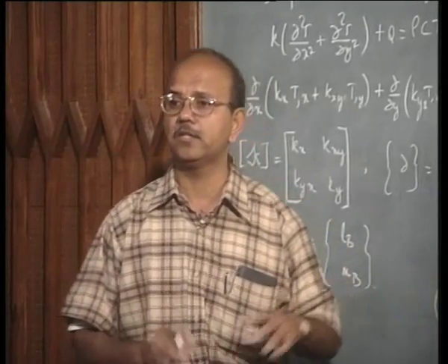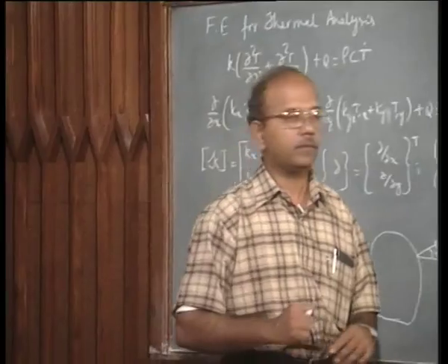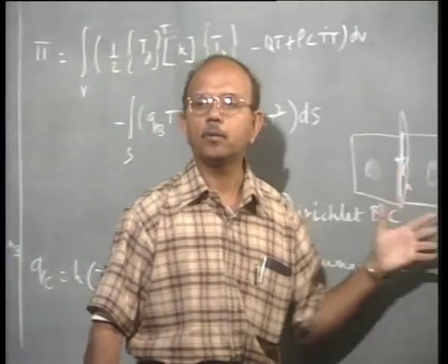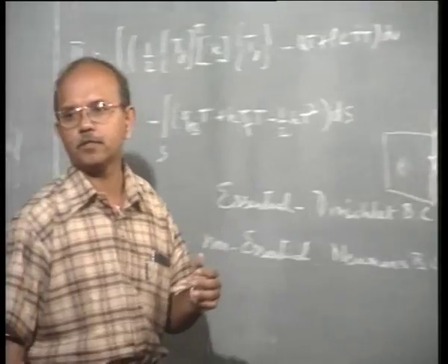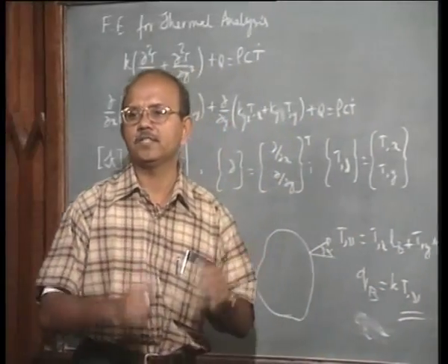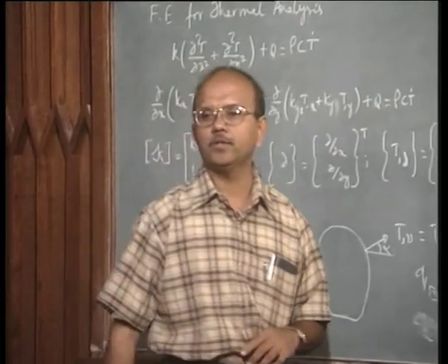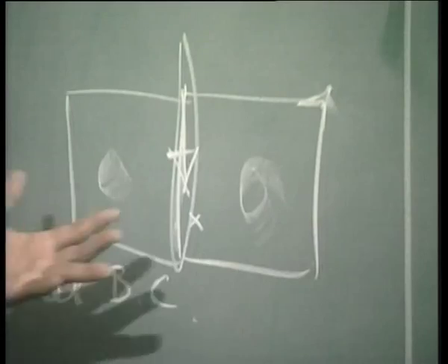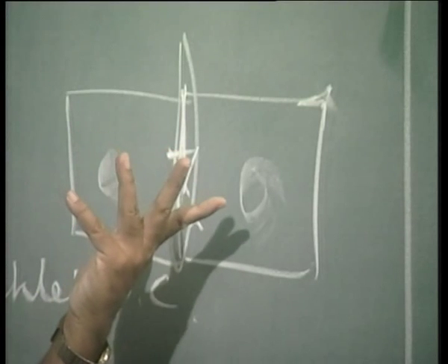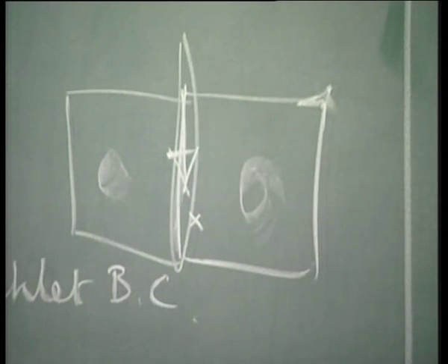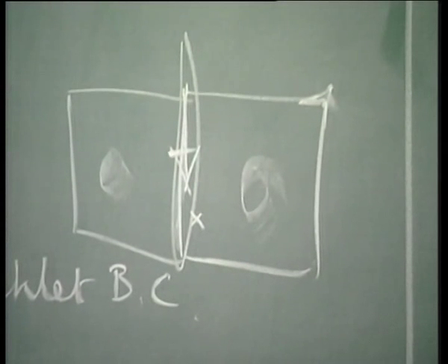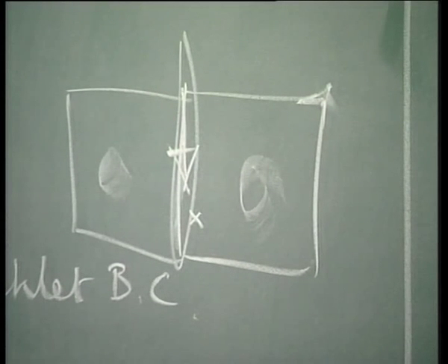So these are the boundary conditions that you give. It is very important you recognize what boundary condition you give. And one of our friends here asked what about the initial condition? Obviously for this problem you have to specify the initial condition as well. So what can you take as an initial condition? Ambient temperature. Unless you do some preheating or something else, we can assume that the sheet has what we call the ambient temperature.